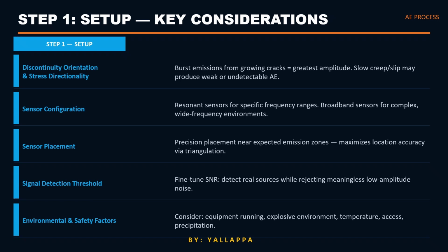If the threshold is too low, you collect excessive noise. If it is too high, you may miss real acoustic emissions. And finally, environmental conditions must always be considered. Things like vibration, electrical noise, nearby equipment, and temperature all affect AE results.